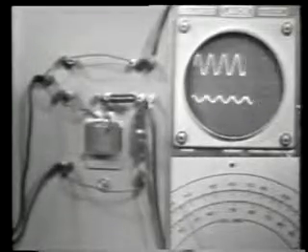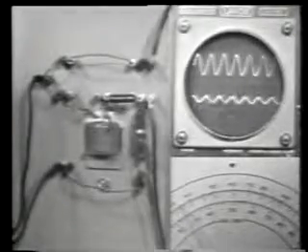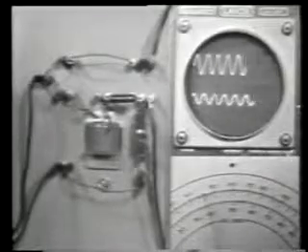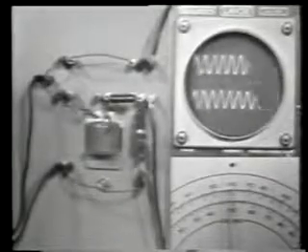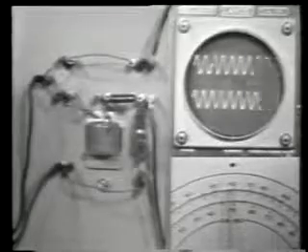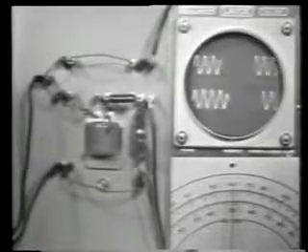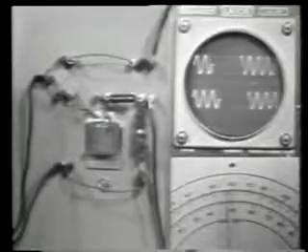Now, at frequencies below 500 hertz, the output drops to minimum, as you can see. Now, as I increase the generator frequency, you'll note the outputs start to rise until at about 600 hertz, the output is maximum. As a matter of fact, it's about the same as our input frequency at this point. A further increase in frequency causes the output voltage to decrease again. So we're passing just this small band of frequencies between 500 and 700 hertz.